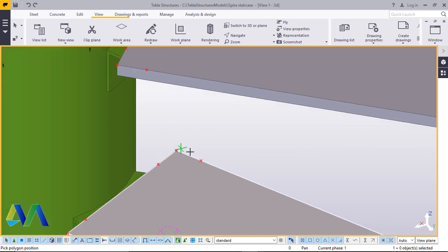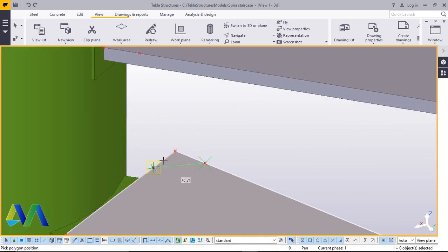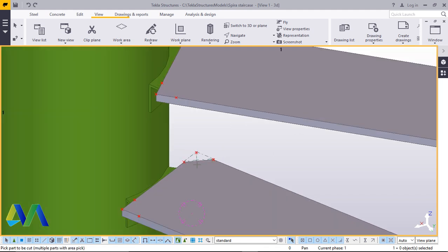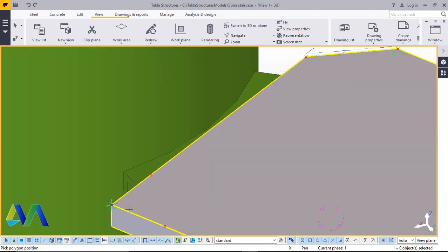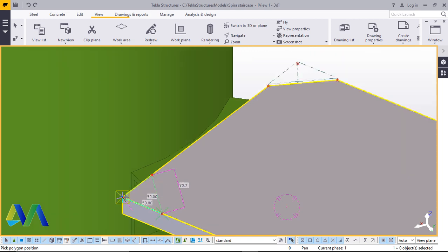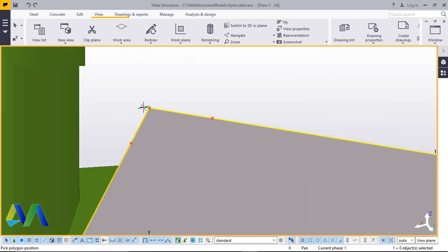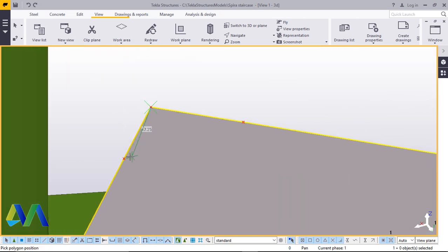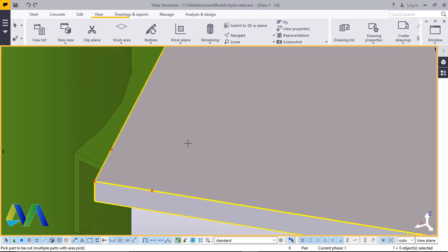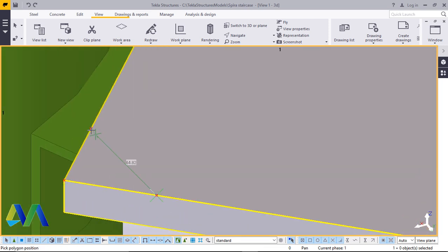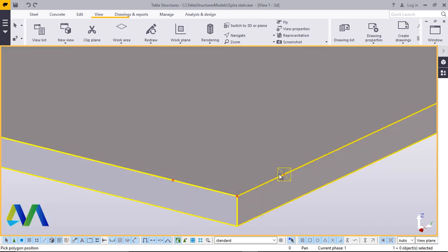Click on this, snap right there, and here. Click on that, snap right there, here, and back to your initial spot, and it will be chamfered off. Click on the part you want to chamfer, or to trim off, or to cut off the unwanted part. Then do your polygon cut like this, the unwanted sharp ends.